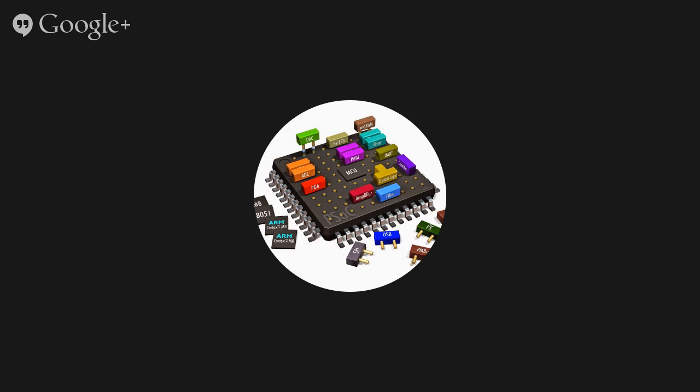So I'm going to save, go back to my top design, and generate this application. So I go to Build, Generate Application. What this is going to do is produce all of my generated source code. So all of the APIs Goggins told you about, all the setup, now shows up here in my Workspace Explorer. This is the LED, so these are all the header and C source files that I got from placing this pin on the schematic.